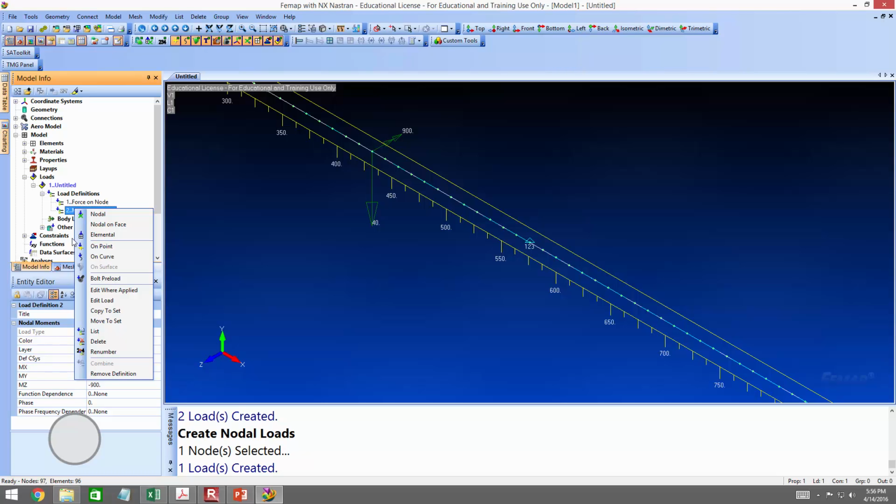We'll get to that here in a second. Look, hold on. First off, a couple things. We do know it's exact because we said we wanted an element every 12 inches. So we know that's the right point. You see what I mean? It's an even discretization. My point that I was making, though, is that that's on the wrong one. Again, you go over here on the model tree, go to model, then your loads, and keep dropping down. Just delete them and start over.